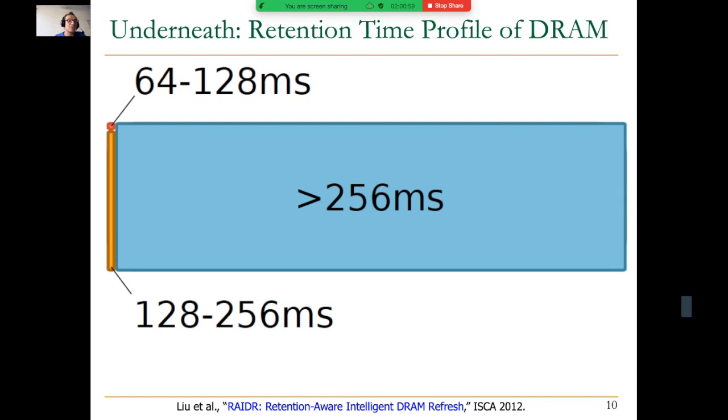It's worst case thinking because we don't have any other interface, any other way of discovering how often you should refresh DRAM cells today. So it's easy to say, I'm going to refresh everything every 64 milliseconds and every single cell will work. But that's overdoing it for cells that can retain data for 10 seconds. And if you look at this, it's actually kind of proportional, meaning you can pretty much reduce your refresh rate by 4x, in this case, 256 milliseconds, as you can see, and lose data only for a very small fraction of DRAM cells, right? That's the idea over here.